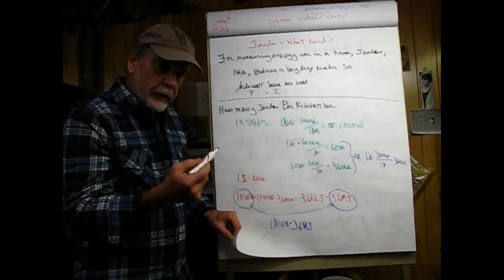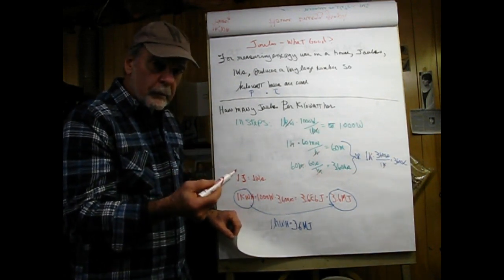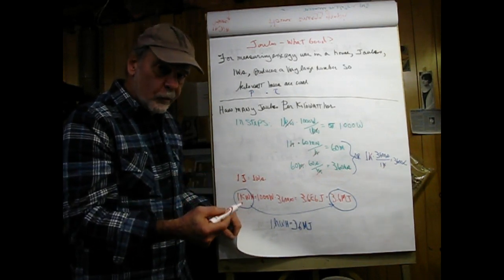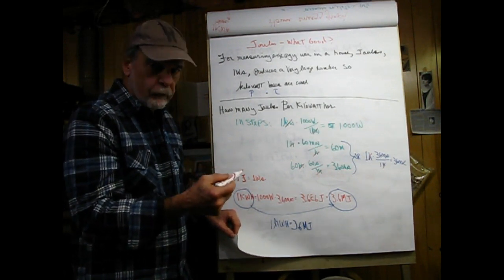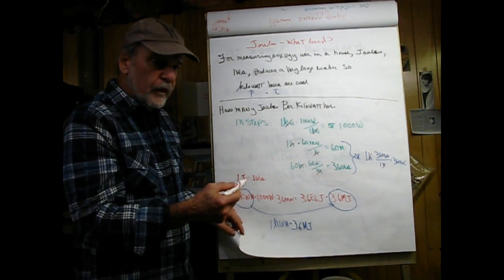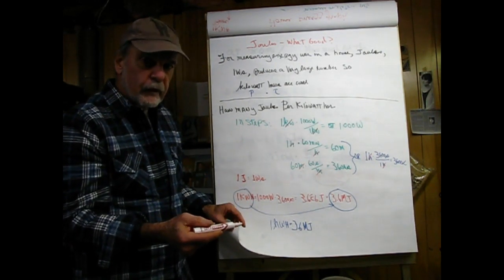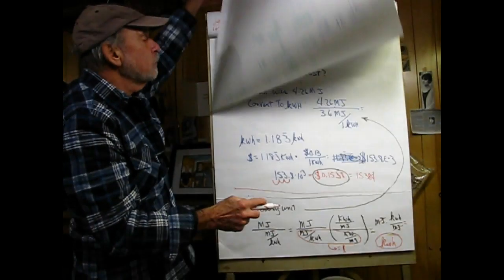The amount of energy needed to move an electron, say from the valence band to the conduction band, can also be measured in joules, except that number is extremely small. So there's another transformation into the electron volt. And that's a measure of energy also, but instead of ending up with a very small amount of joules, we talk about electron volts in reasonable numbers like we do kilowatt hours.